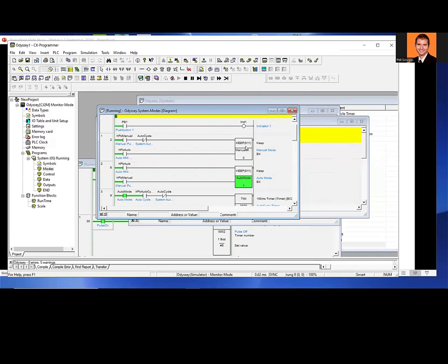So here I'm looking at something called a keep. And a keep is the same thing, if you're a Siemens programmer, as the set reset block, which Allen Bradley doesn't have anything like that. They have a latch or an unlatch, but this is one block that keeps your set and reset together. So that's kind of nice. And again, Omron calls it a keep. You've got to remember all these instructions would be converted from Japanese. So instead of saying latch, unlatch, set, reset, they just say keep, right? They're mnemonic for a holding relay.